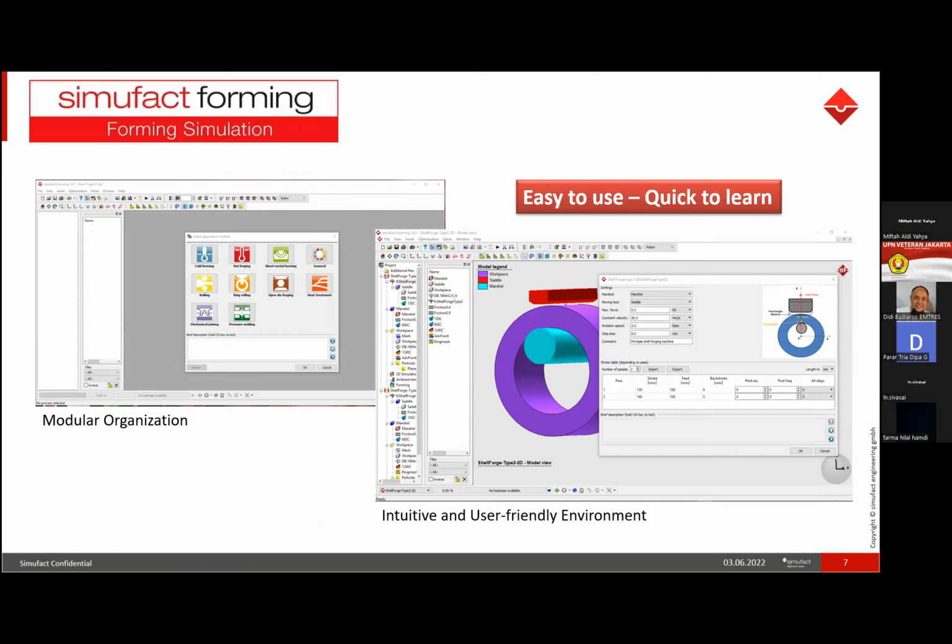Now, one great advantage of SIMUFACT forming, which we got from user feedback, is that it is really user friendly. The type of input that SIMUFACT asks for is exactly a particular operating parameter. Even though it is FEA, finite element analysis software, the FEA part has been tuned in the background for experimental users, so that people can concentrate on the experiment parameters rather than on the FEA parameters. The same thing can also be used by an advanced FEA person, because he can access the solver through subroutines and try out different variations.